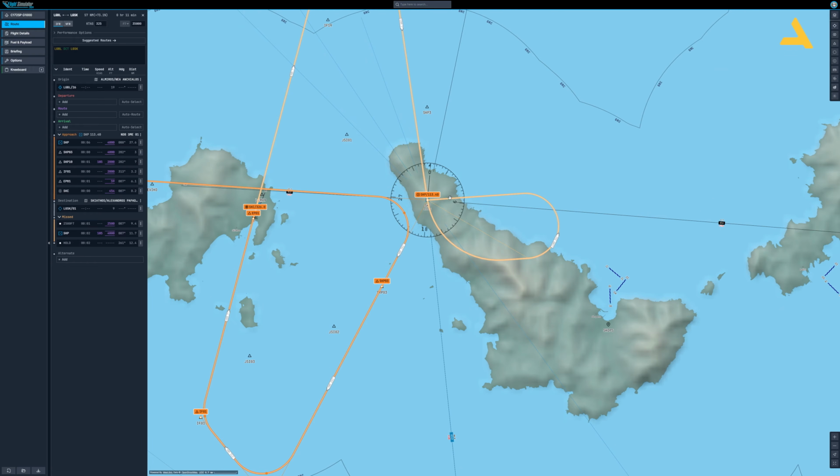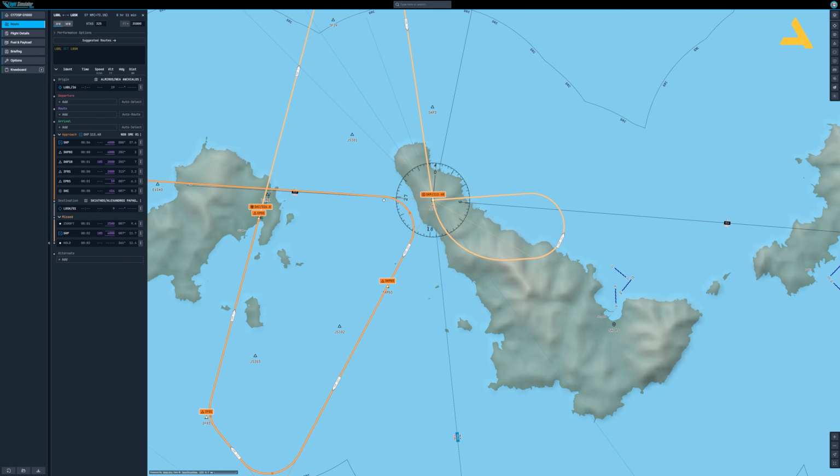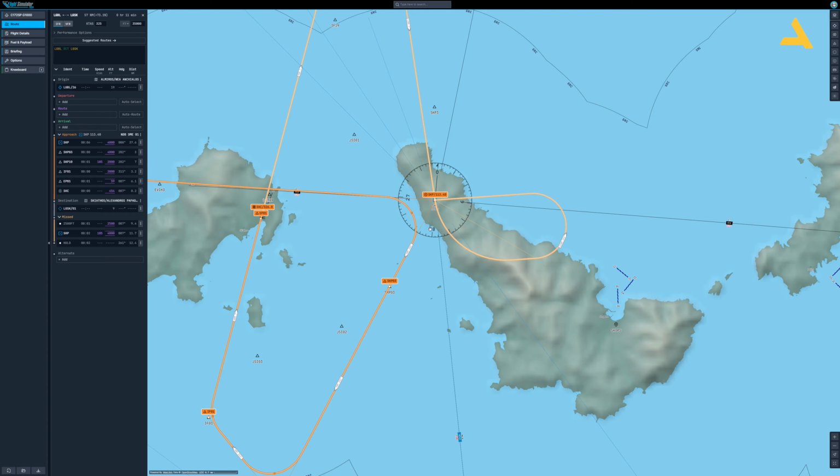If you extend this line, you're actually tracking it in 88 degrees. You're going away from this VOR. There is also an inbound radial for this VOR. You have to basically add 180 degrees to 88 to get the reciprocal of it. So if I add 180 to 88, you'll get 268. So the inbound radial for this VOR is 268. So that's how you basically do the VOR navigation.